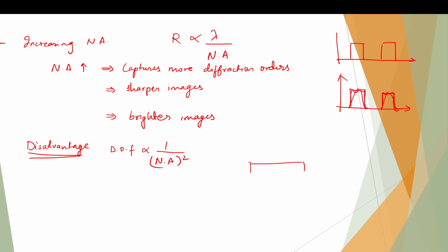and the topmost layer is my photoresist. Now this photoresist thickness need not be very uniform. Some places it is thinner, some places it is thicker. This deposition variation is coming because of the underlying layers or whatever reasons. Then what happens is, some places will get exposed better compared to some other places. So the yield will depend on the depth of focus of the projection instrument.